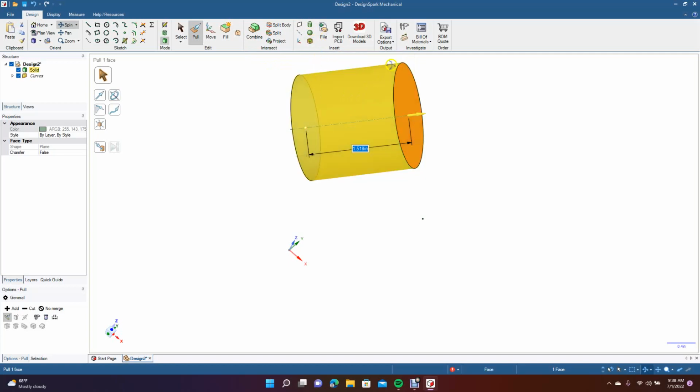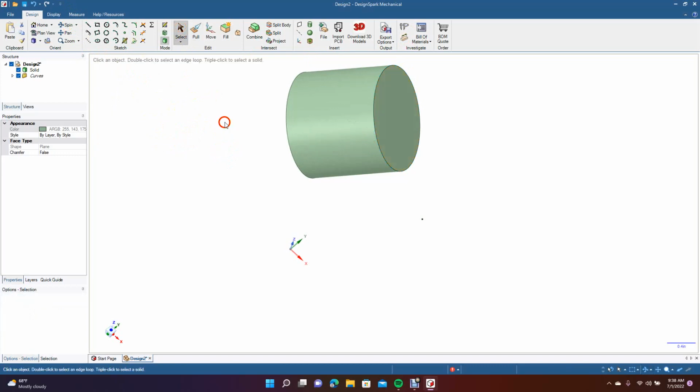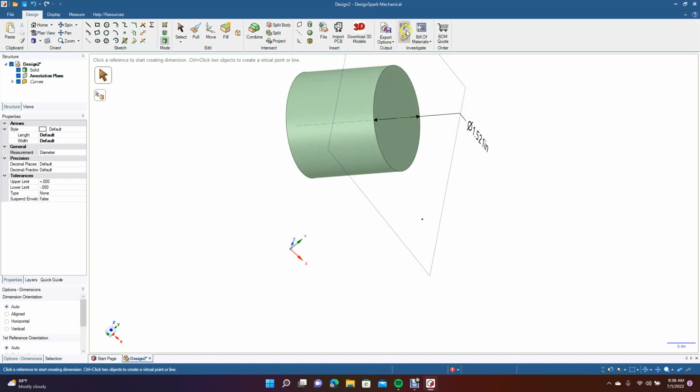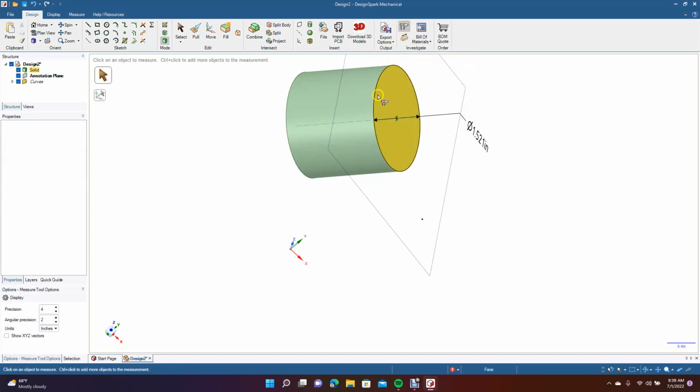The only thing we haven't gone over is these tools down here. These are basically just measuring tools. Let's go ahead and click off. So basically this tool here just measures. You can click on a couple of points, and you'll get a measurement. Or you can use your calipers. Your calipers, if you click on any piece, it displays a little box in the lower corner, and it tells you perimeter area.